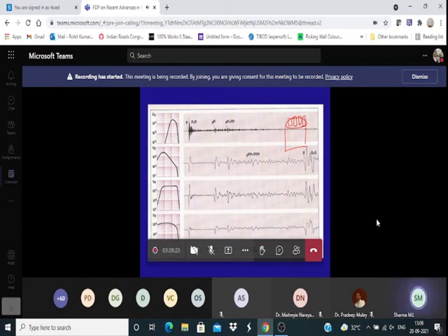Okay, having different characteristics. So the first one, the characteristic was this. It means that it was passing all these but rejecting all this. Okay, so only the high frequency around 10 to say 50 hertz, they were recorded. So the seismogram will look like this. Now here in this case, it is rejecting all the higher ones, but recording faithfully these ones.